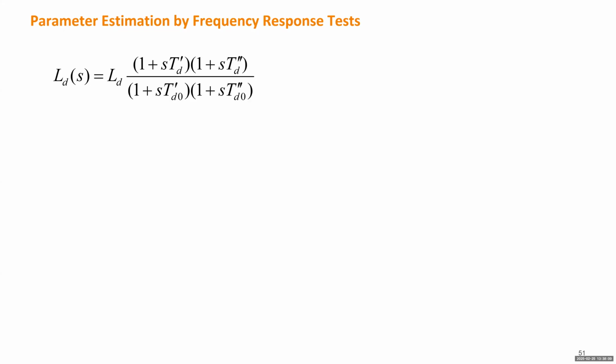But there could be two concerns. The first one is when they do such testing, they put it in their test bed. That doesn't represent how the generator behaves in a real power system. Actually, the same problem is also true for a lot of renewable generators, such as solar farms or wind farms. The model they give you is only accurate for very small systems. They set up a very small environment to test the parameters. But when you connect to a large grid, some parameters need to be identified again. You have to do what we call model validation.